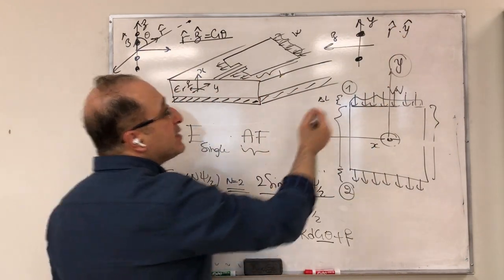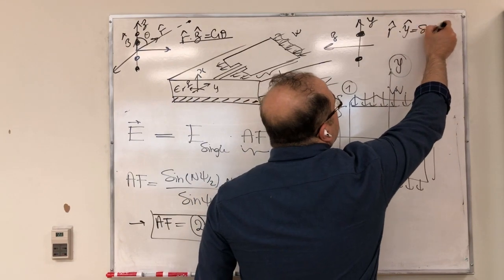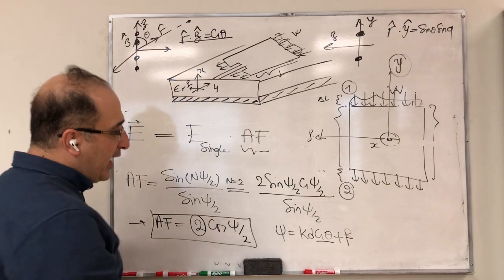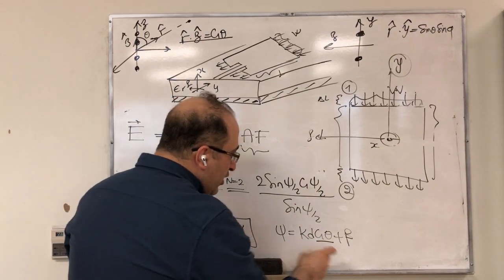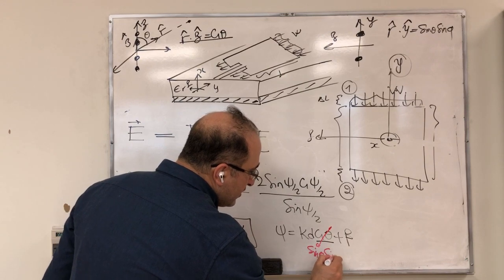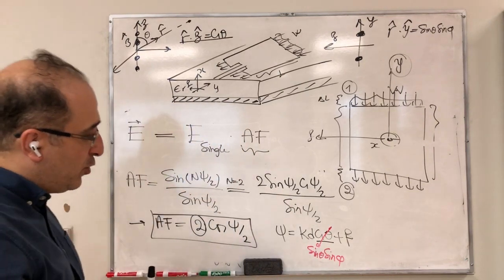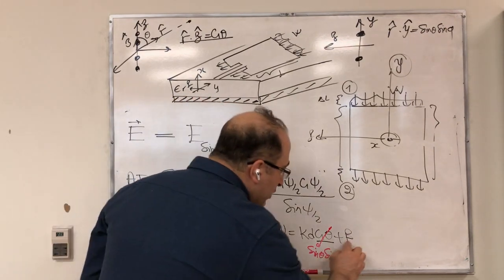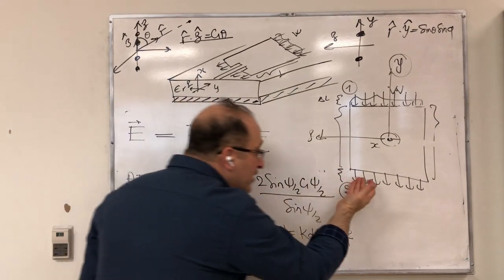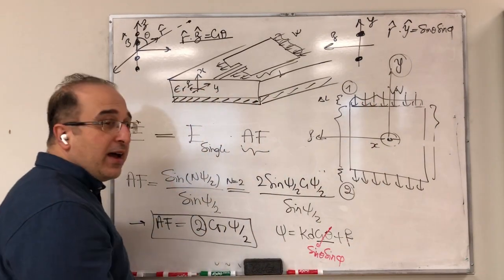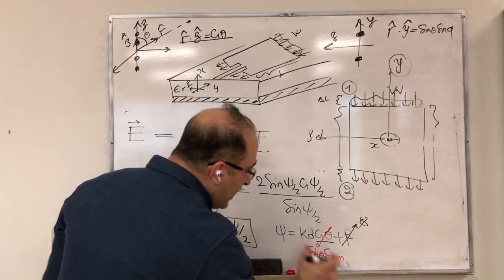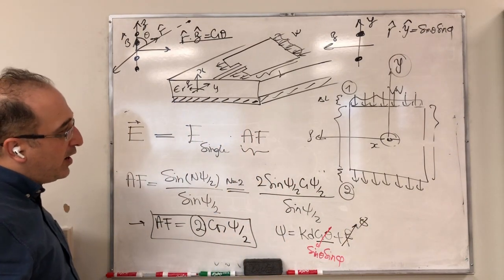And if you do this, you get sine theta sine phi. That's going to be r hat dotted with phi hat. So in this expression, you're going to change cos theta to sine theta sine phi. And that's your sine theta sine phi. And what is beta? Beta is the phase difference between these two. But we mentioned in the previous lecture that these are in fact in phase. So the phase difference is 0. So you get actually kd sine theta sine phi.